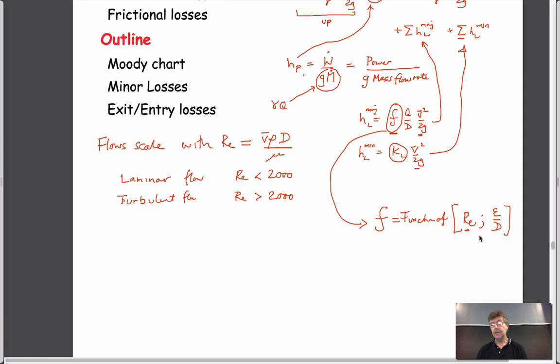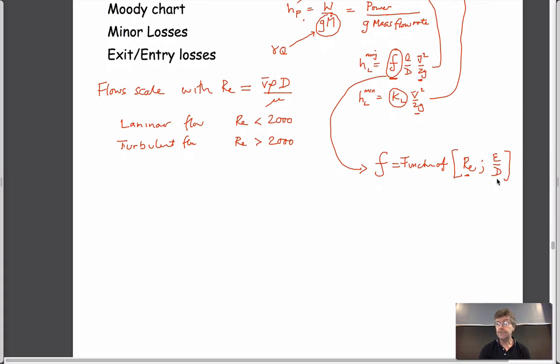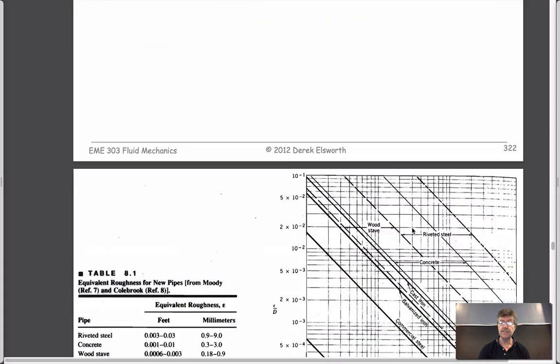And so we've used this analog before. The reason for golf balls being dimpled is that it makes a turbulent boundary layer, which actually makes the golf ball more efficient in going through the air in terms of less drag, and triggering that turbulent flow by the dimples is what gives it that behavior. And so the relative roughness, we can see, is a property that we'd like to figure out.